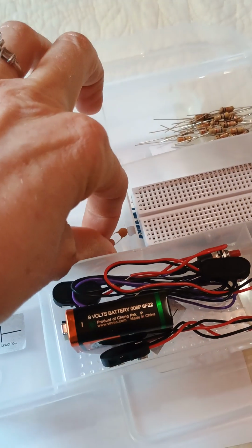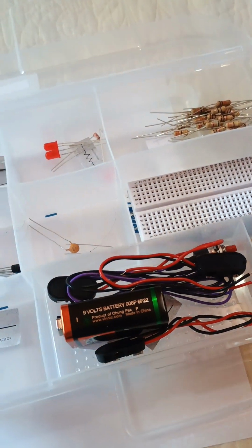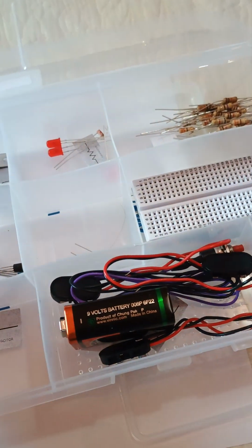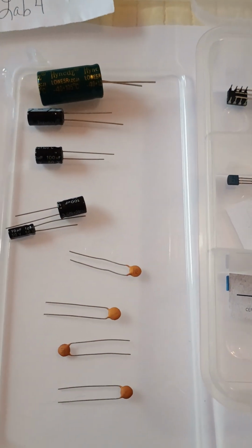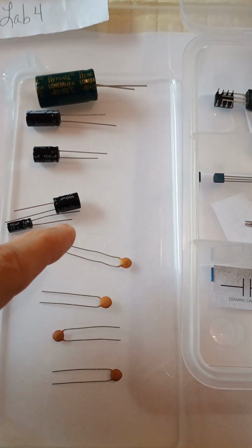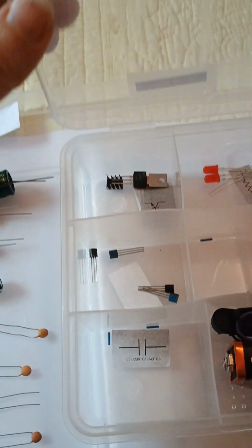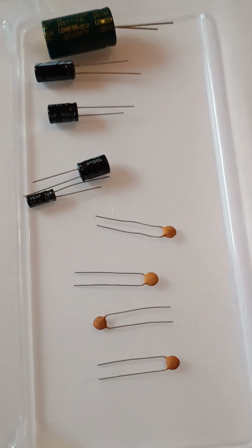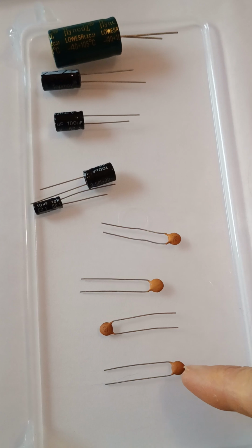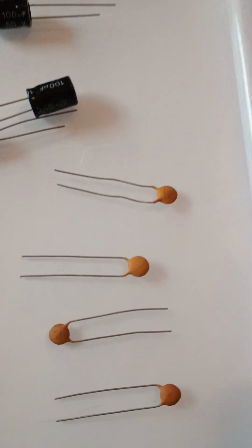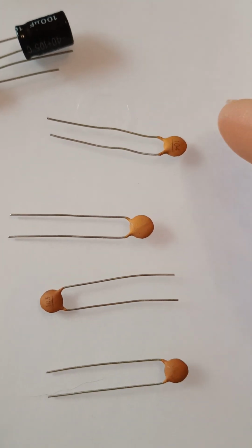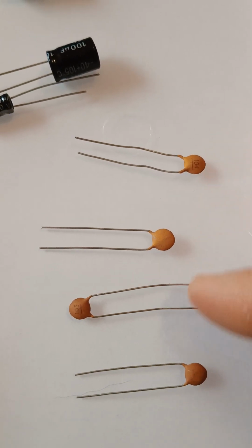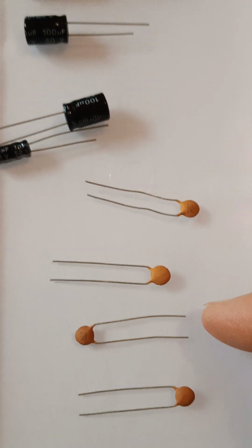All right, so your other capacitors look a little different. They're a lot smaller than those. So if you're having trouble with remembering the electrolytic capacitors, once you have all 9 of those out, let's count them. 1, 2, 3, 4, 5, 6, 7, 8, 9. You can slide your parts box out of the way, and we'll just take a look at these. So these are the ceramic capacitors, and if you'll notice, it's a little bit hard to see, but you can see the second one right here says 103. The one up top says 104. We're going to learn about that value and how to calculate that value in just a moment.